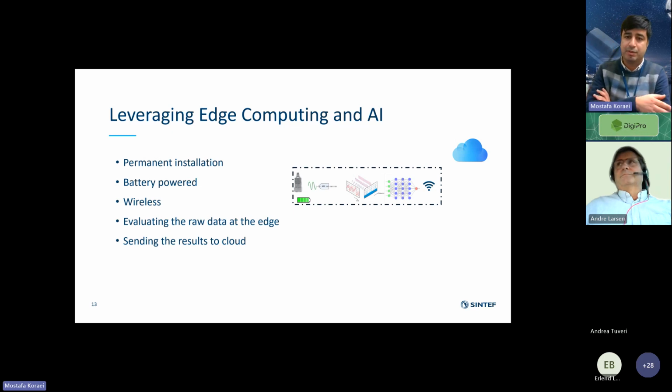So yes, when we attach the system to the bogies, we detect lots of vibration from all over the terrain, but we isolate them in a digital board. We cannot isolate them at the sensor side, but we can isolate them on the edge computing system. What we just need to know is the mechanical structure of the system that we are measuring the vibration in, and also the speed of the main rotating parts of that system. It is the direct way, or we can also do some signal processing to detect it indirectly on the signal and then isolate those parts from the rest of the vibration.